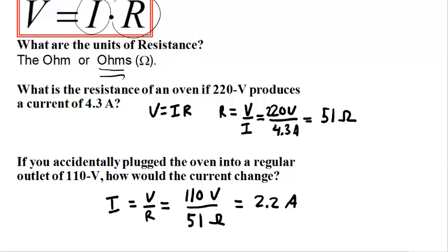Just a bit of a side note, the regular amount of electricity, voltage that we get in a household is 110 to 120 volts. So by default you can say 120 volts anytime we're using something in the home. There's also a second line that comes into the house for certain appliances that need a lot of voltage, and so those will be from 220 to 240 volts. Very few things actually need it. The dryer is one that comes to mind, and your oven.